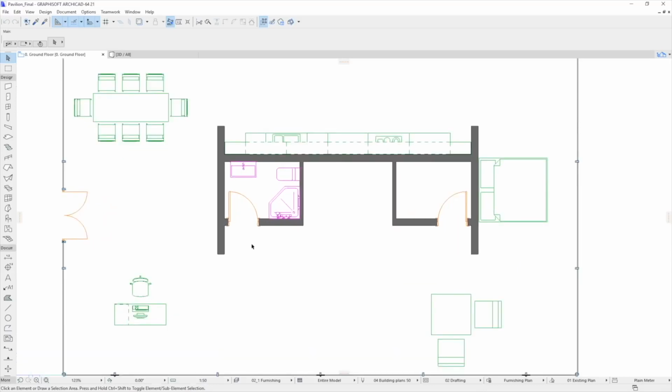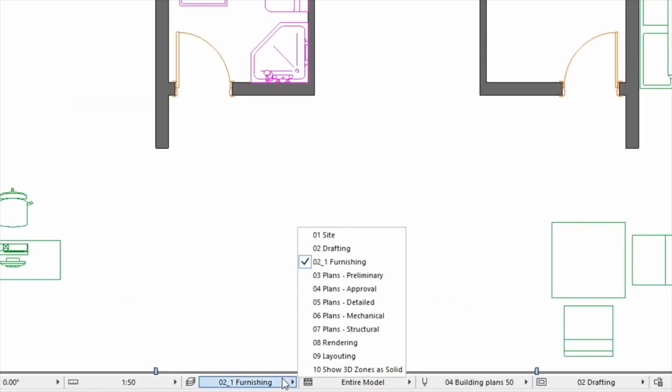One obvious difference is all dimensions, elevation, and section markers have disappeared. These were on some layers that were switched off when changing to the views of the Furnishing Plans folder. Layers are like vellums of old times, layered on top of each other. If we pull one item out of the stack, it will be invisible. Elements that have common characteristics, like exterior walls, interior walls, furniture, etc., should be placed on a common layer so that their visibility can be regulated together.